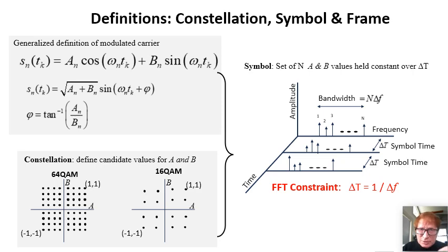Something curious that came to my attention, and we will say more about this later, is that there are 64 digital samples taken at 20 megahertz for a waveform with 20 megahertz bandwidth. From our Nyquist theory, we would expect that we cannot resolve the A and B values from the sample data set. We should sample at twice the bandwidth. Isn't this correct? We'll say more about this later.